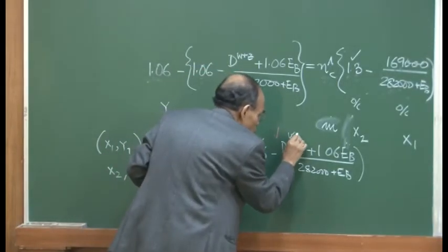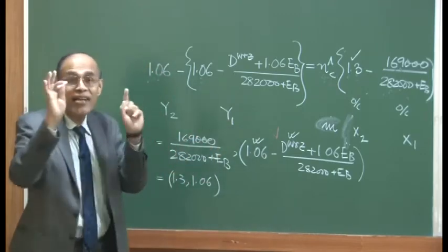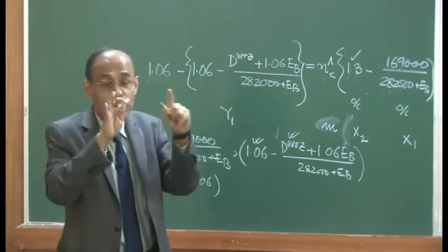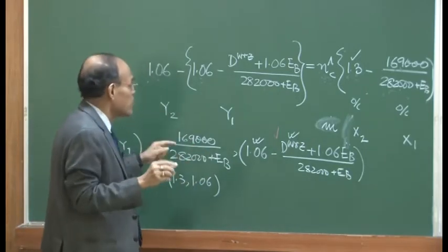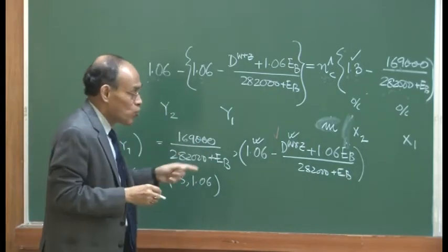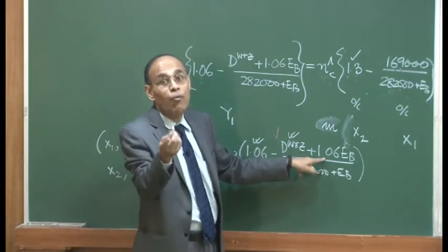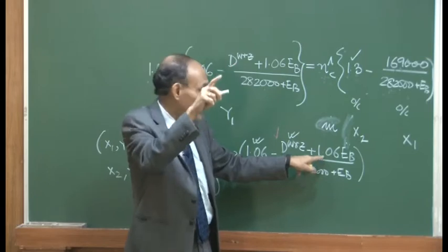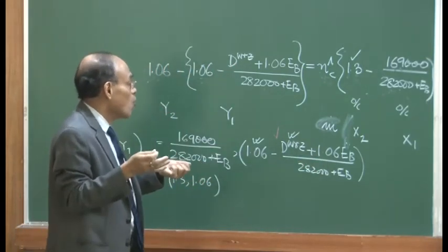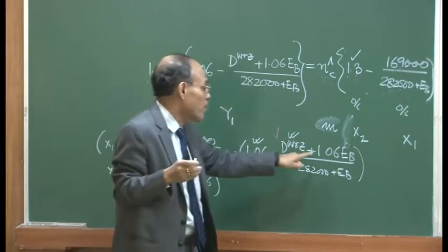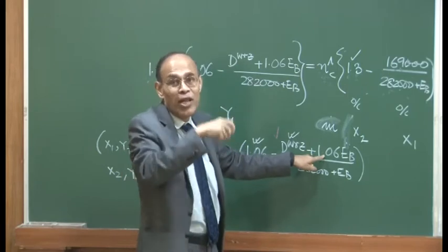this dWRZ, they will depend on practice. This is the expression for idealized blast furnace operation when Fe2O3 is the feed and we do not have any impurities present, and it is a very simplified scenario. So, the coefficient of Eb, 1.06, will change the moment you change the feed. Okay? So, therefore, O by Fe, for example, you have used, and you have a blast furnace where you are charging in, for example, some metallic Fe also into the blast furnace itself.